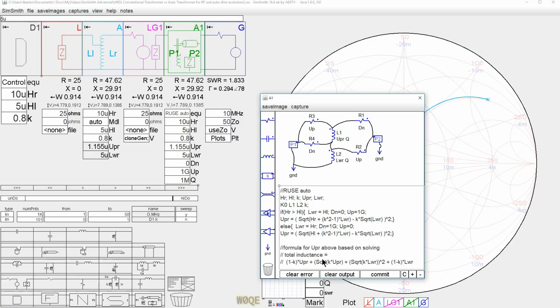And this formula is based on this. The total inductance in a string like this, if you broke this string up to be a coupled inductance and a leakage inductance, the upper inductor would have a 1 minus K times the upper inductance value. That would be leakage. Then K times the upper is the part that gets coupled to the K times the lower value. So we take the square root of that. That converts it effectively into turns. We take the turns, we add the turns up, we get it, and then we square it again and get back to inductance.